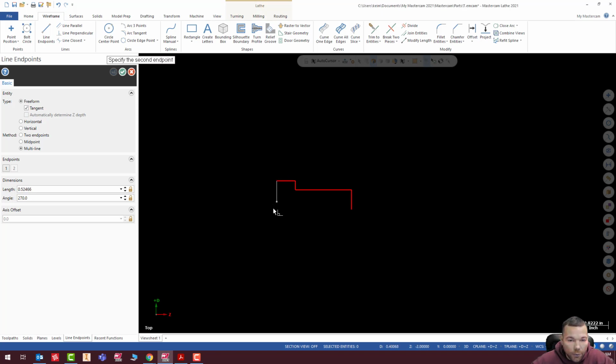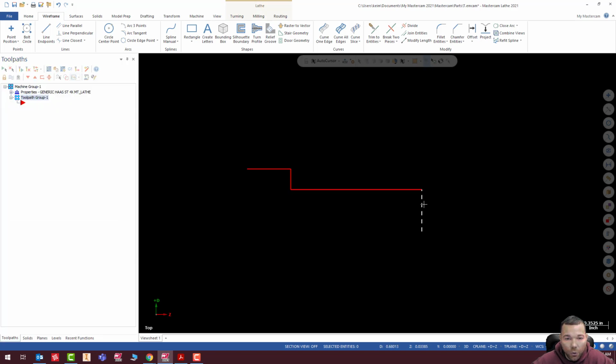Okay. I do not need to connect this. There's no real need to do that. The only reason I might do something like that is if I had a profile back here, or if I wanted to put a chamfer on the back side. I can do that, as you may have seen in other videos, and I'll do it in this one. I'll put a small chamfer to deburr that edge on this back edge. I'll do that with my cutoff tool. All right, so I'm just going to hit check, and that is all you need.